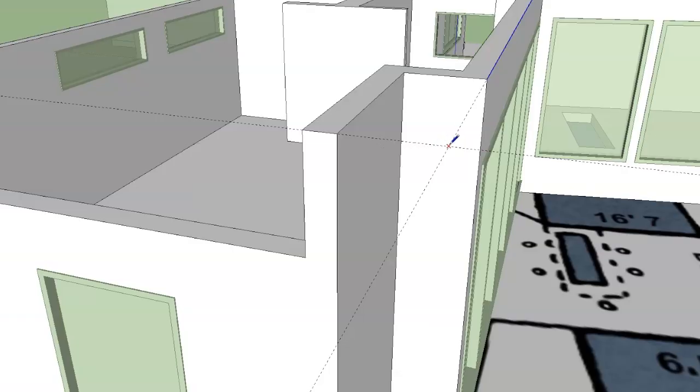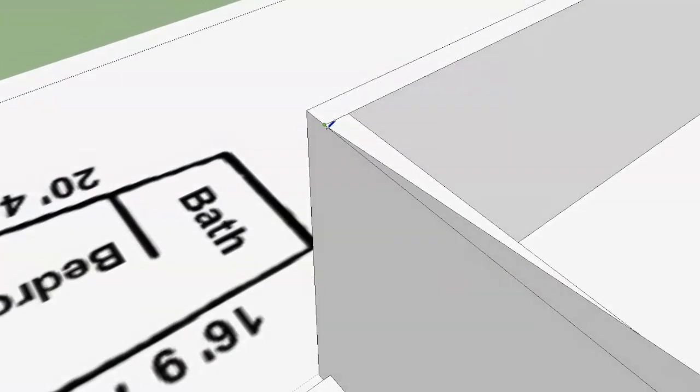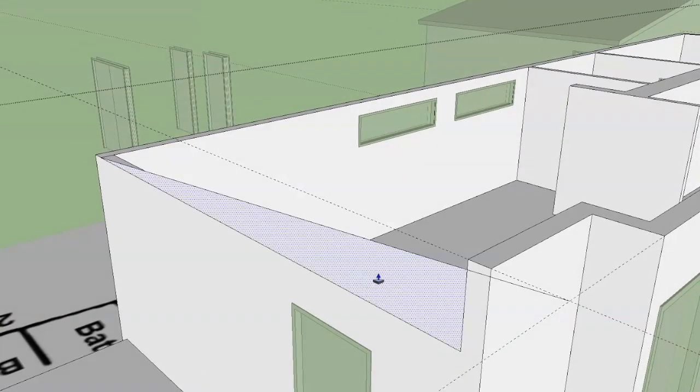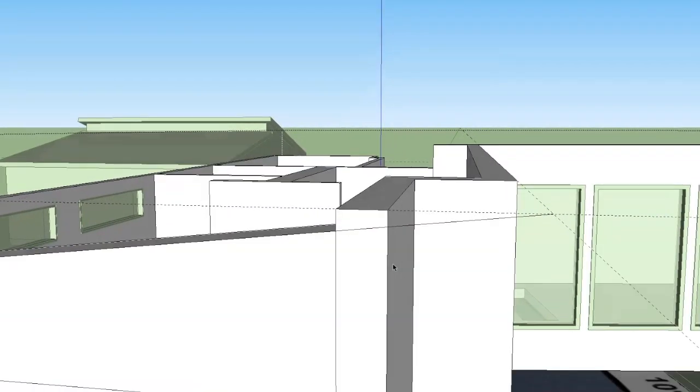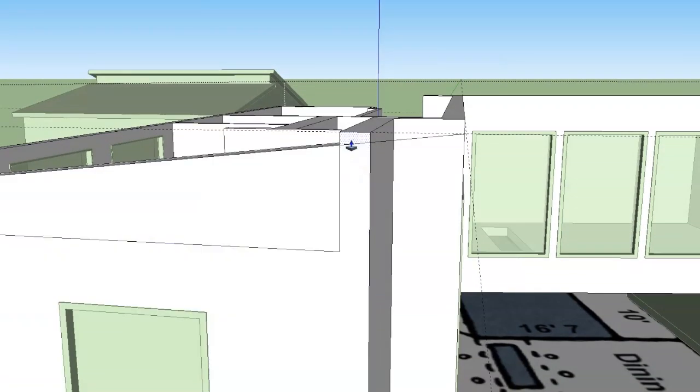We want it to stop at that point right there on the interior part of this wall. Otherwise, we would have to raise the rest of that interior wall up to meet it, and it gets a little bit weird. So we're just going to go on the interior part right now. So we'll select this point right here with the line tool and draw it down to right here. And there we go. That has immediately given us that shape. We're going to take that shape and pull it back 6 inches to line up with our exterior wall. And then what we've done here is this part of the wall right here, you can see this wall is too tall because it's still at 10 feet, but the slope has already started to come down.